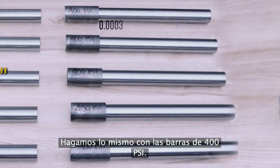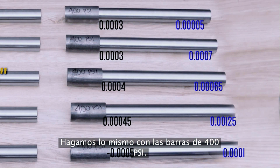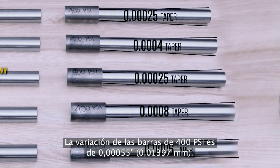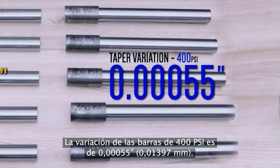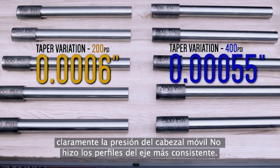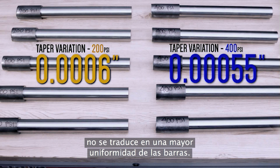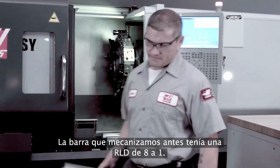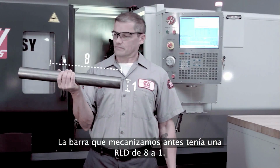Now let's do the same thing for the 400 psi shafts. We find the taper for each shaft and compare these values. The 400 psi shafts vary by 5.5 tenths. Maybe this seems surprising, but we can clearly see that more tailstock pressure did not make the shaft profiles any more consistent. The large shaft that we just cut had a supported L to D of 8:1.